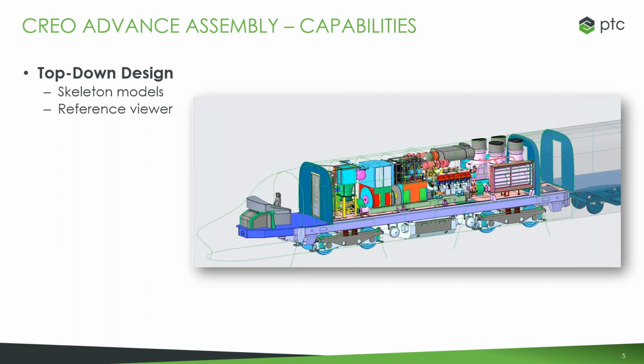You can actually graphically visualize dependencies and relations to understand change propagation. So you can share the referenced geometry into each group, so you have control over what's being referenced, and then they can view it and understand, right? If you go to make a change in the late stage, you can understand what everything's referencing, parent-child relationships. And this is where you get that control.